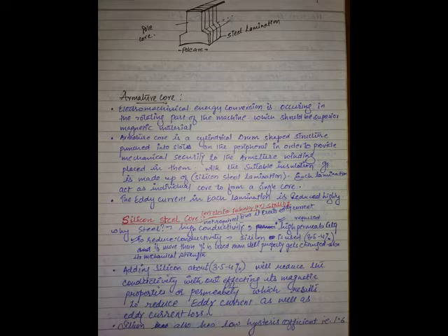If you say this is a coil, this is one side of a coil, known as a coil side. So two coil sides are making one coil. Two coil sides are connected to one commutator segment. If there are 10 coils, how many commutator segments will you have? Simple. Is it clear? If you have 10 coils in the machine, you will have 10 segments.